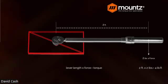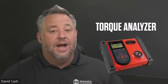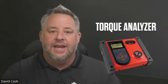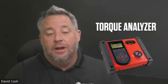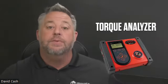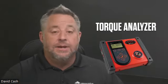So that's how we actually measure torque, but we also use torque analyzers to do this as well. And what a torque analyzer does is it actually takes the analog signal from the tool and converts it to a digital signal, and that gives us our torque output that we can see.